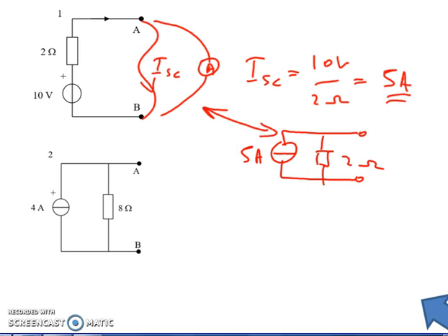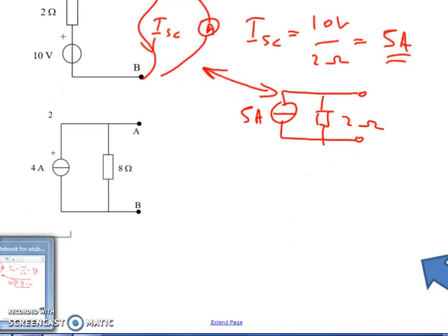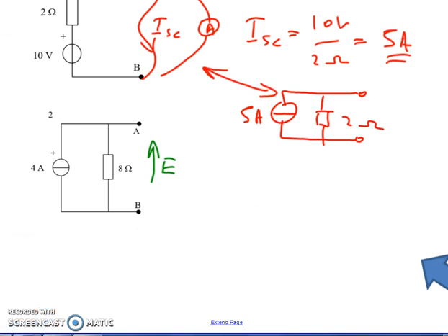For the Norton circuit shown below, we can convert that to a Thevenin circuit simply by measuring the EMF that appears at the terminals of the circuit. All the current from the constant current generator must pass around that loop if no load is connected.